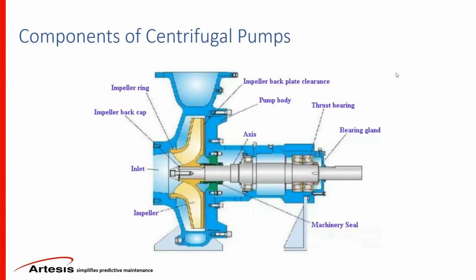All right, so in the impeller, there are several key components that we should keep an eye on to keep track of the mechanical performance of the pump itself. And this can also be seen through the electrical signature analysis. If you have problems with your impeller or bearings or bearing housing or the seals, this can actually be seen through the spectrum analysis.